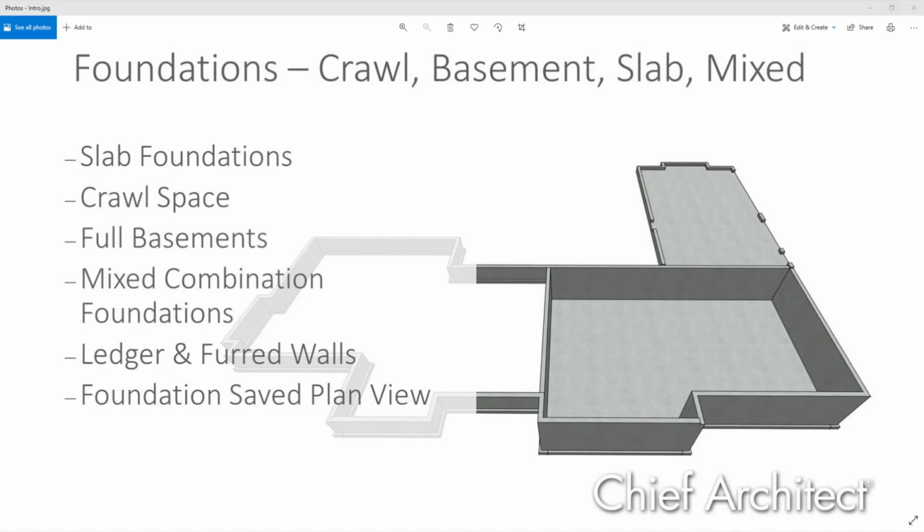In the wall definition, you can make it a furred wall, but the problem I have is that up here in Massachusetts, we have to drop the footing down 48 inches below the grade, in this case below the cellar slab for a walkout, and then that furred wall is traveling down with it.